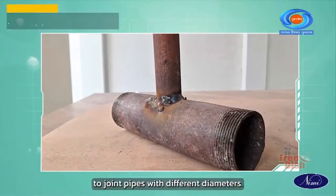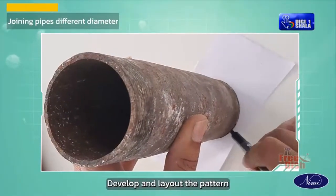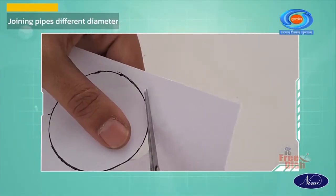Let us now learn to join pipes with different diameters. Develop and lay out the pattern for the 90-degree T-pipes with a cutout on the main pipe by parallel line development.